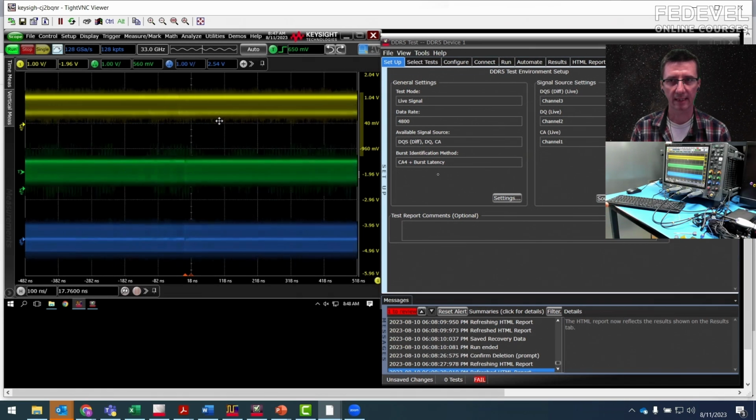And also, I think there is timing which has to be found out for how far each memory chip is when you are doing address access or something like this. Yeah, because if you use flyby technology, then all the memory chips are at different distances from the memory controller.